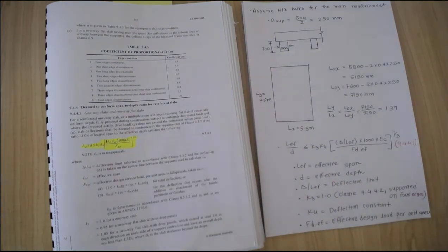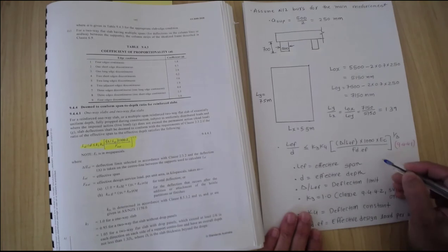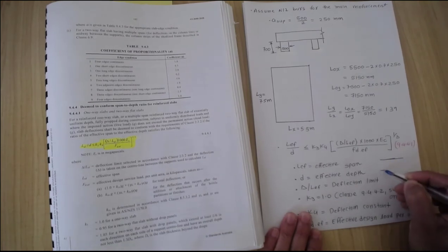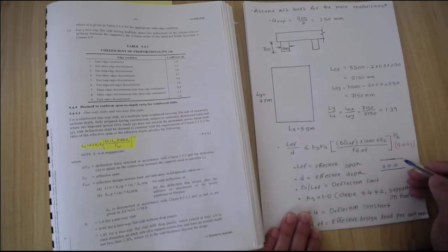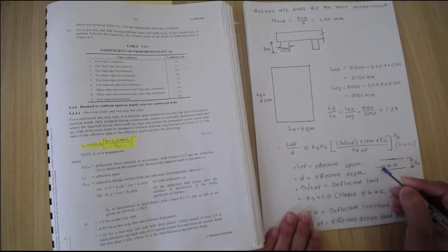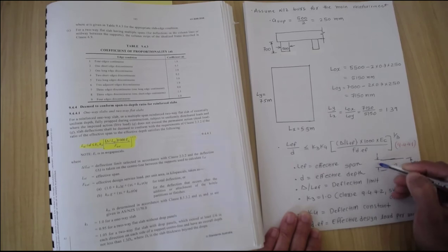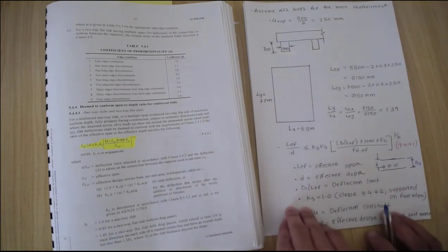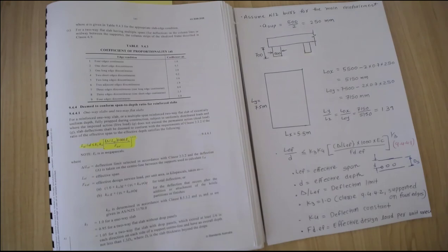Now for the effective depth, I can draw a small picture here. If you are talking about the depth of the slab, then we assume these N12 bars here. So this total depth is denoted as Ds, which is the depth of the slab. Now the effective depth is measured from the center of the bar to the top edge. So the effective depth is Ds, take away half of this reinforcement, take away this cover, which gives me this small d, the effective depth. We will calculate that one in due course.